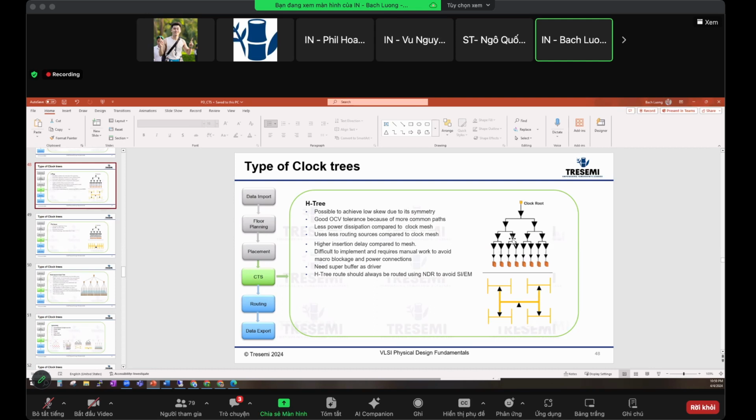We call it the trunk. Okay, and there's another term called top. If you have a spinal thing, you have a big long one. The top is basically these guys from the source to the buffer. So the rest of these are trunk and these are leaves. That's what it meant. So when you say connect the leaves pin using this rule, this is what it's talking about, this level, and the trunk is the rest of these guys. And then there's another terminal called top. If you don't specify the top, it's going to use the same as the trunk.